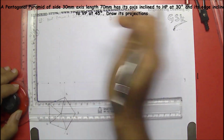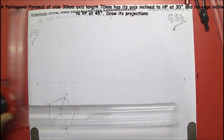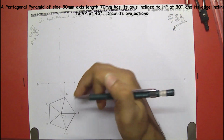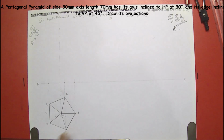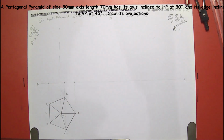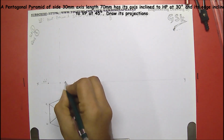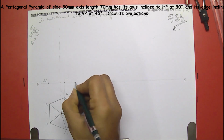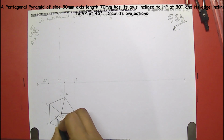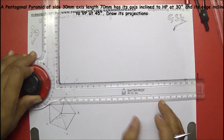So in the initial condition, I'll be making this one rest on the HP. So the bottom base would be falling on the reference line XY. This would be B dash, A dash. This would become C dash, E dash, and this would become D dash, and this is O2 dash. And the height of the pyramid is 70.